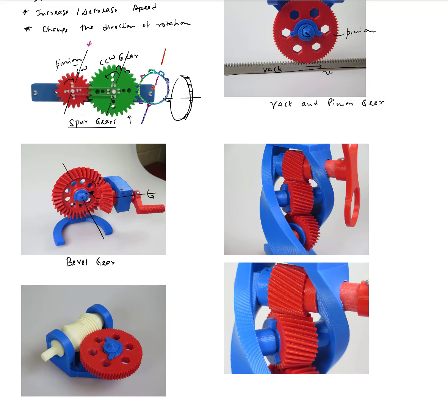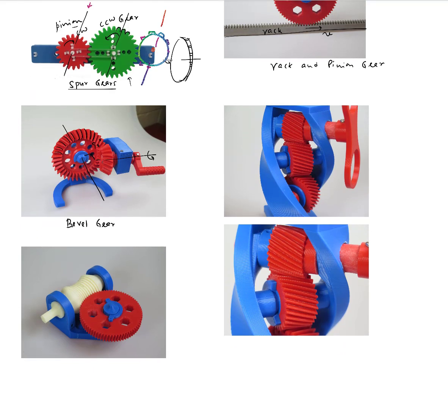The other thing you would notice with this particular gear system is that the teeth over here are actually at an angle. They are forming some sort of helix. And the advantage of a helix kind of angle as opposed to a straight cut angle is that there is a gradual contact between the teeth, and that gives rise to smoother and less noisy operation, which in turn increases the torque carrying capabilities of these kinds of gearing system. You can see the same kind of teeth in a 4th kind of gear over here.